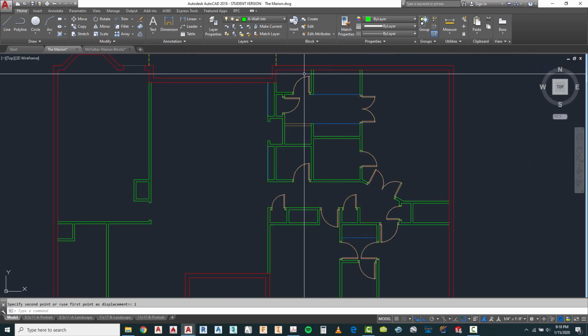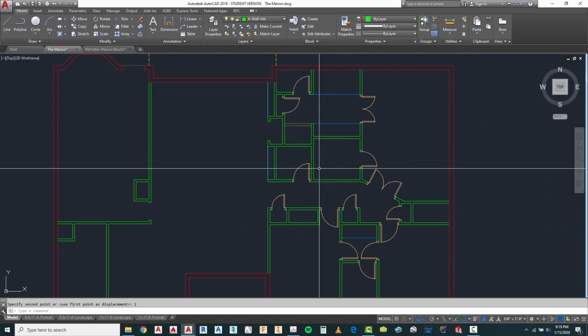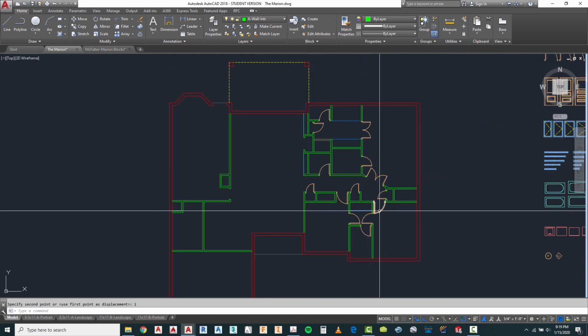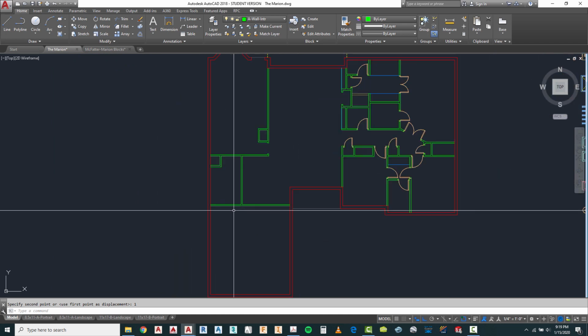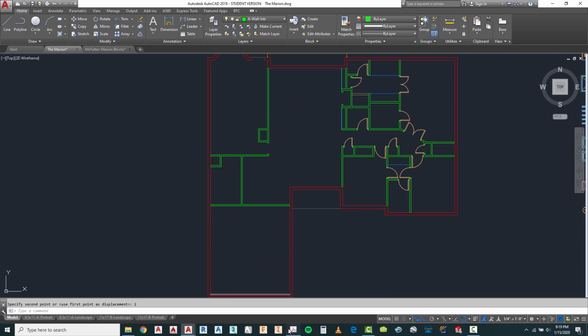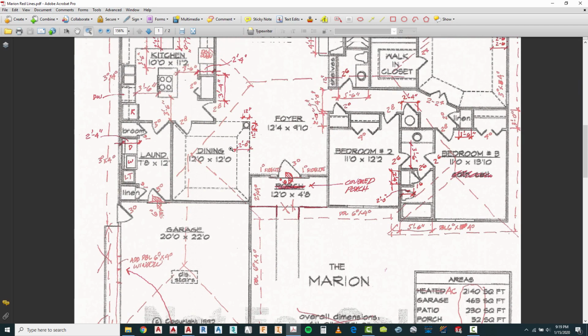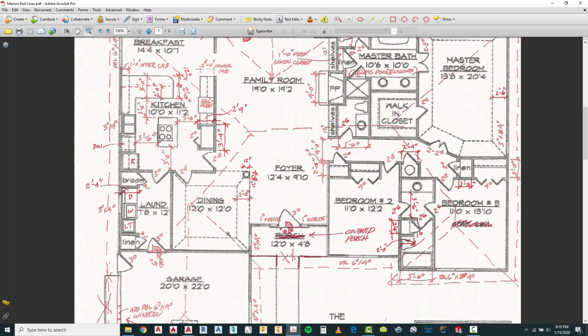Let's continue around. I think we've got all our doors that we wanted into these spaces for now, once again with that exception. So let's work our way over to here. Let's take a look at our drawing and let's see what we've got happening over in this area right here. If you notice, going from the garage to the laundry room, we have a 3-foot door. We also have one coming out of the laundry into the kitchen, which is 3 feet. And we do that because it makes it a little bit easier to bring the washer and dryer and the appliances in through there.